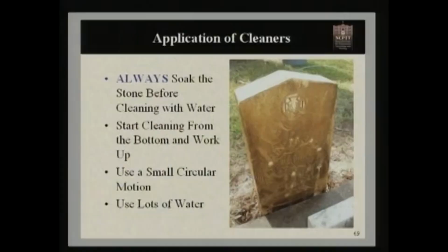So we talked a little bit about the cleaners. Let's actually talk about the methods behind the application of the cleaners and the actual cleaning of a headstone. One of the most important things is we always want to soak the stone with water before the cleaning. Stone is incredibly porous. It absorbs a lot of water. So we want to make sure this stone is completely saturated before we apply the cleaner. And this is also important to keep the cleaner right on the surface. That actually saves us money. We use less cleaner that way.